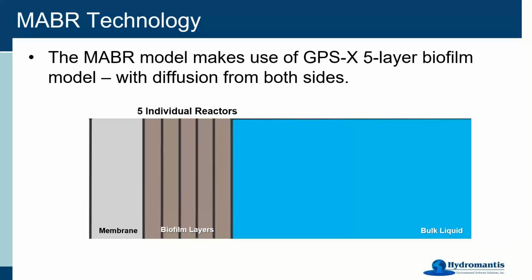Okay, so to cover off the processes that we are including in our mass balance of all of the COD and nitrogen and phosphorus and all the other components, we have, first of all, attachment and detachment of solids. This takes solids that are floating around in the bulk liquid and attaches and detaches them from this first, outermost biofilm layer. This has a rate constant that you can control.